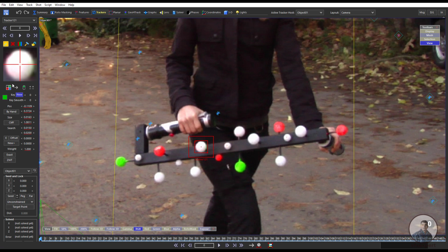Then after this, we have to check the direction, which is that I am going to track forward here. So suppose if you also want to track backward, then you have to change the direction. This direction is important, remember this. This totally depends on your playhead position here. Now suppose you want to track forward or backward, then you can use all these options, or you can use the space bar for forward or backward tracking, even the left and right arrow keys for frame by frame tracking here, okay?